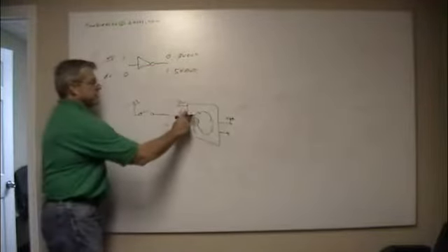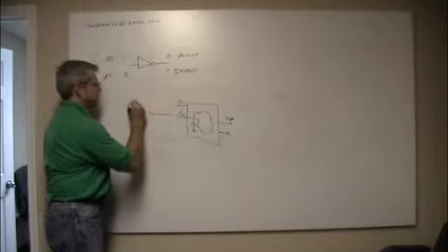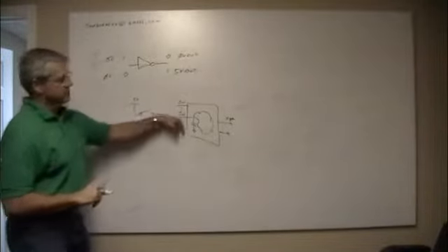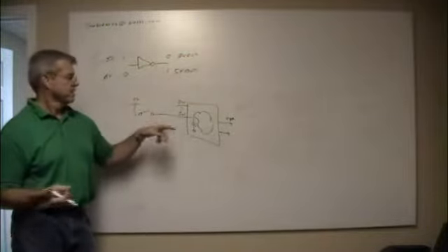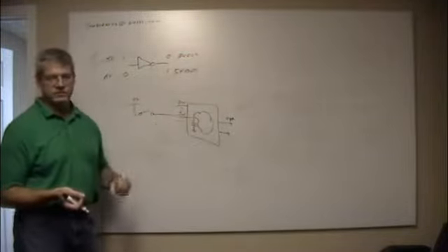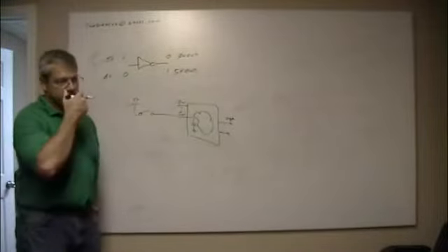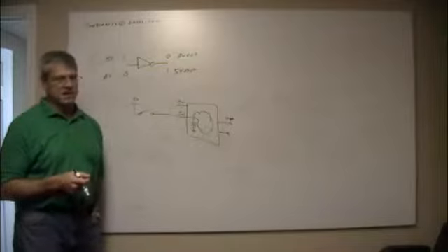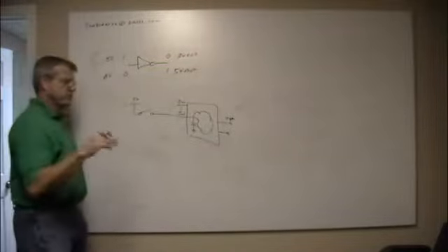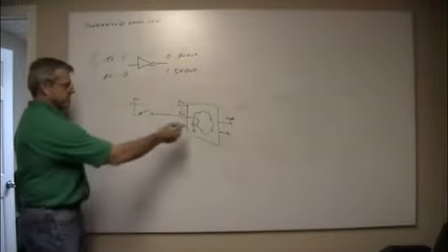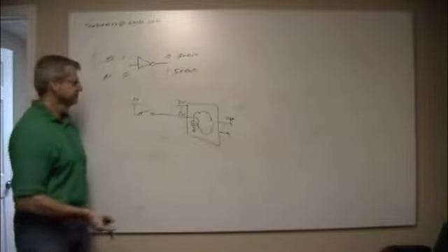But if you don't have this, and this is where I was getting at, if I put 5 volts in and I push the button, that'll charge that up. I let off of it, and there's nowhere for the charge to go. So this will always be 5 volts, at least after the first time you press the button. And the decay time on it is hours sometimes. So one of the things you've got to be careful of when doing maker projects is to make sure there's a way to get this back to a known condition relatively quickly.